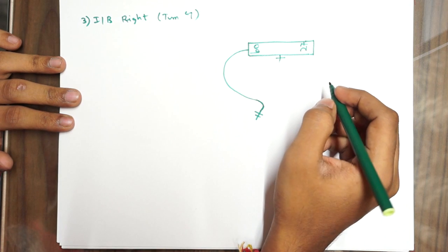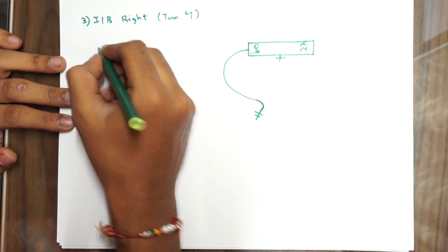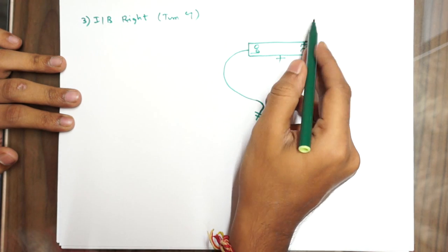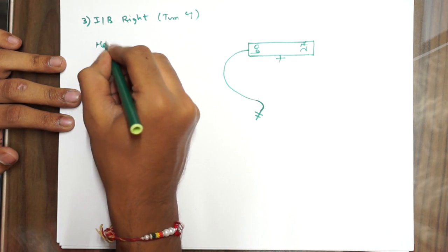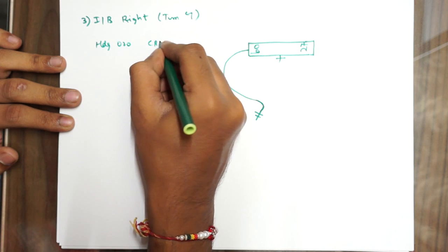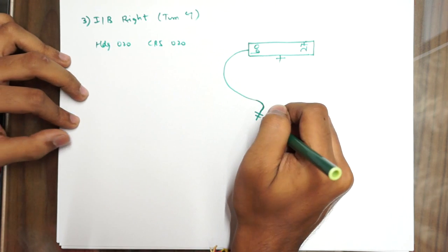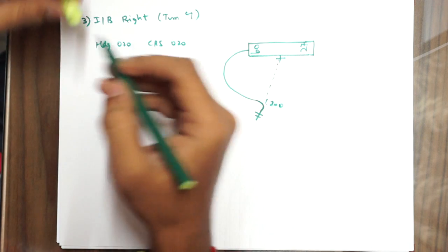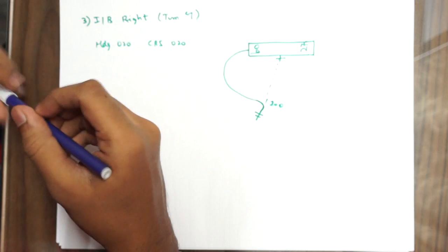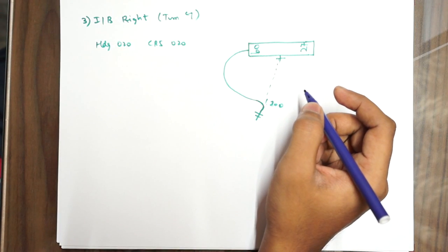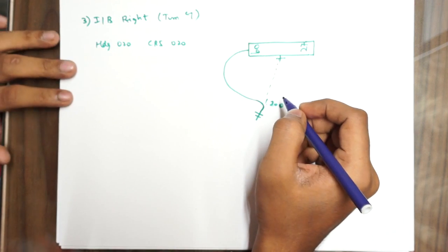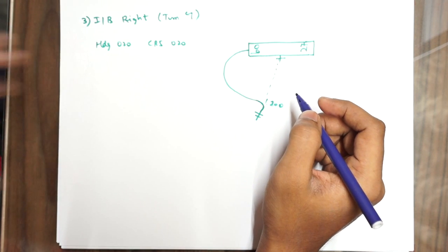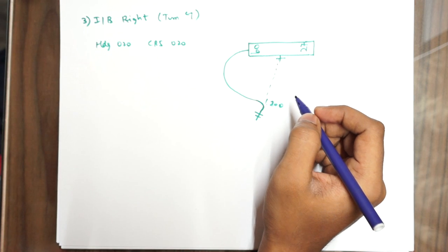Okay, now let's take an example for practice purposes. So if you remember, inbound, you set your heading, let's take the heading at this position as 020, and the course window you set opposite. Say you are on radial 200, this one is 200. Your course window will be set as the opposite. If you remember, I told in the previous radial interception video, inbound it's always opposite. Instructors might teach you different ways, but this is how I do it, and I find it really easy to understand. So I'm just sharing it with you guys.